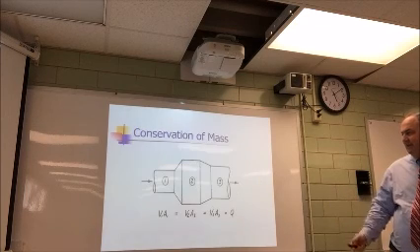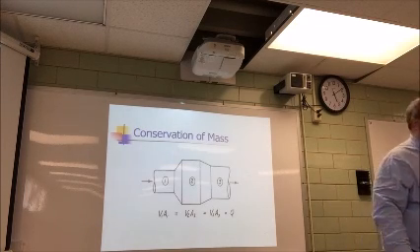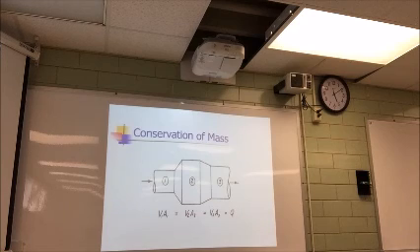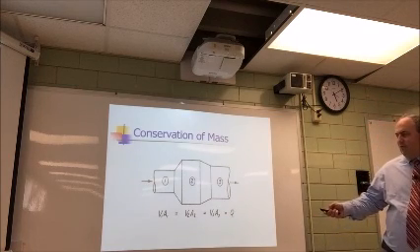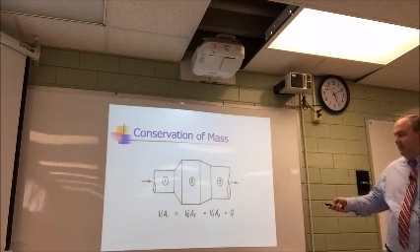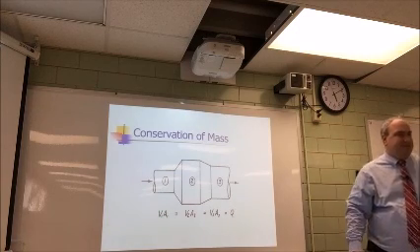Basic equation, right? Here's something you need to understand, and this will not go well with you at first. It's called conservation of mass. So my question: V1 times A1 is equal to V2 times A2, and V3 times A3. What does this equation say? What is the cubic feet per minute in all 3 of these regions?